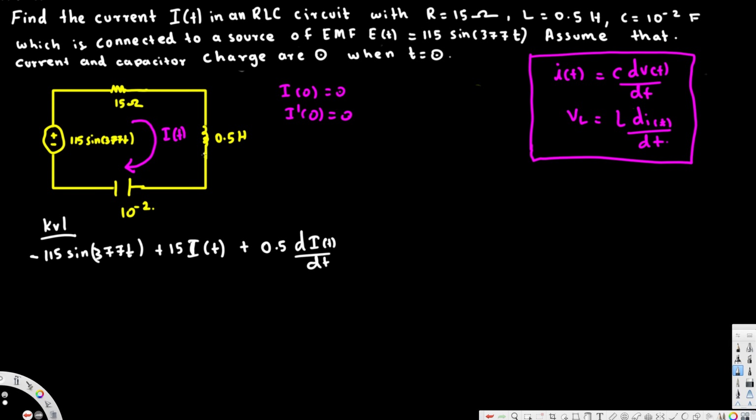Okay, and after that this current is going through this capacitance. Let's go ahead and rearrange this equation first, because we have to express this current in terms of the voltage. If we rearrange, this is going to become I of t divided by C times dt is equal to dv of t, and if we integrate this one, we can get v of t.